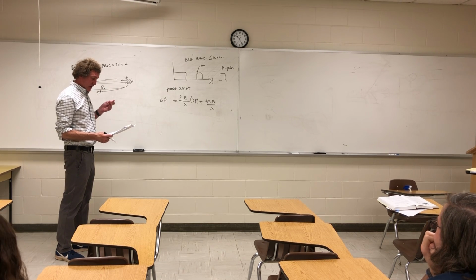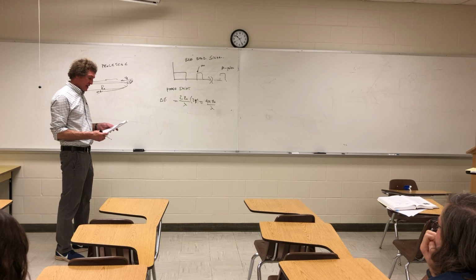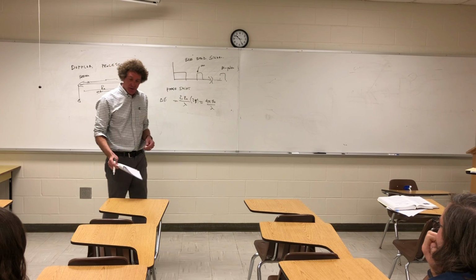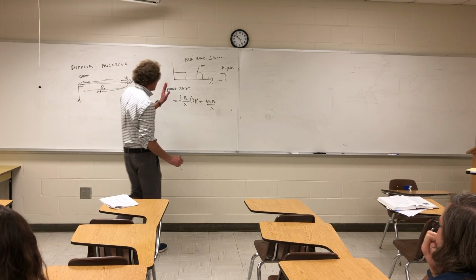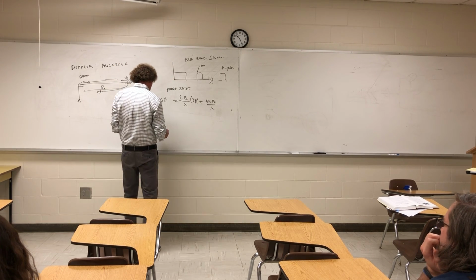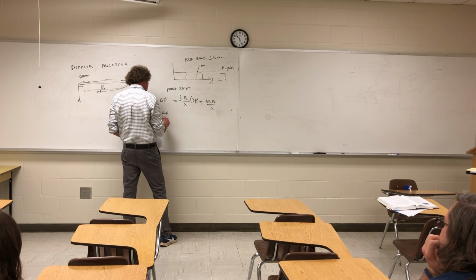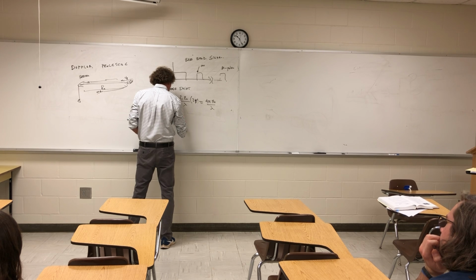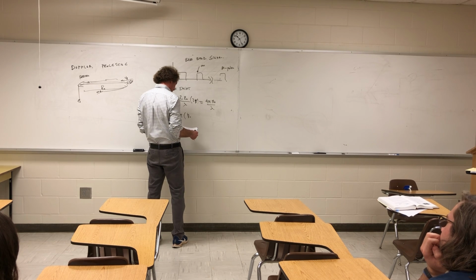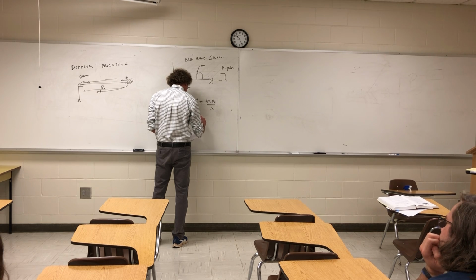Or moves through space. Now, the actual change in phase that happens over the duration of this pulse is this, I should say for any point in pulse. Now we're going to get 4 pi, this is the phase change over the duration of pulse, and that's going to be 4 pi over lambda. But now it's going to be R0 here, and it's minus m times T, the PRI, times V.